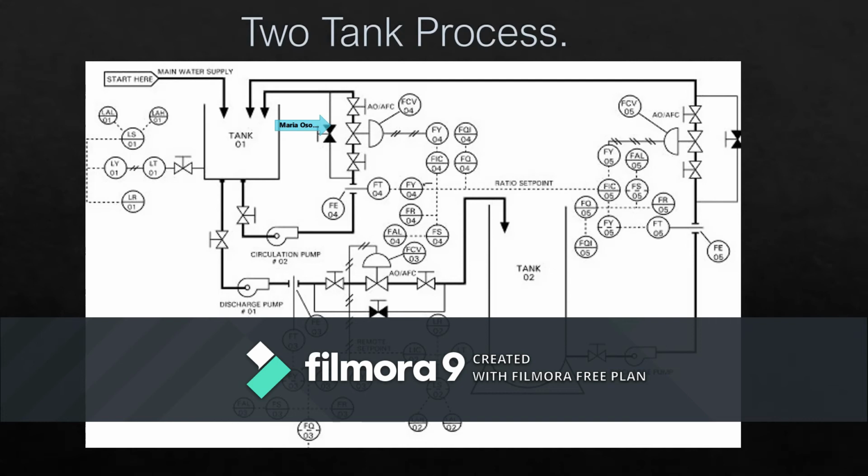The first tank also has a second pump, which is the discharge pump. It also has a flow transmitter with a flow element, and it also has a flow relay to change to an electric signal connected to a flow controller indicator, the flow recorder for flow quantity also, and the flow switch connected to the flow alarm level.